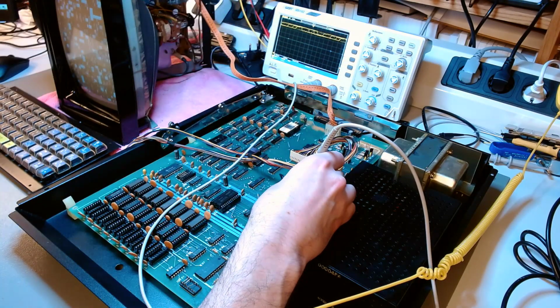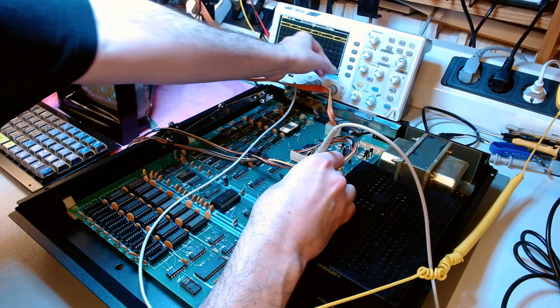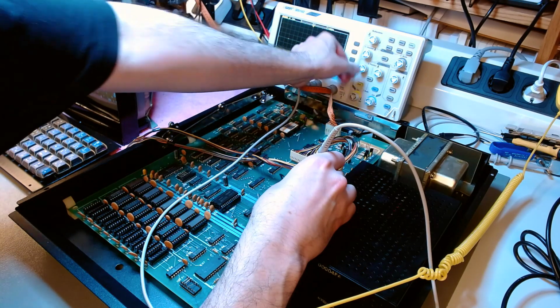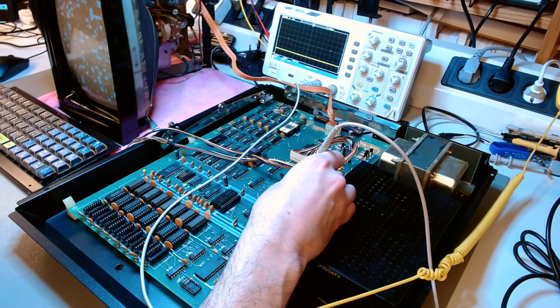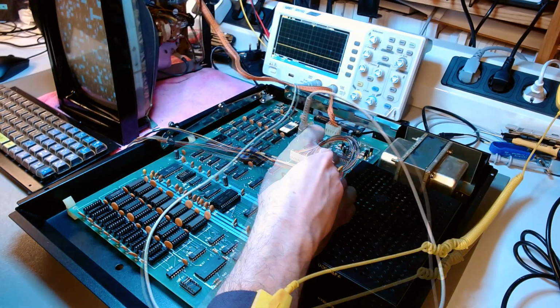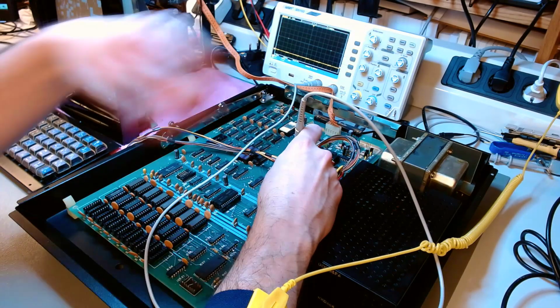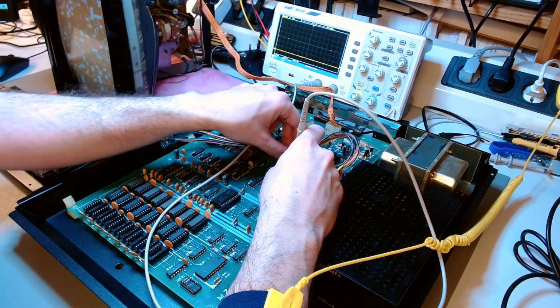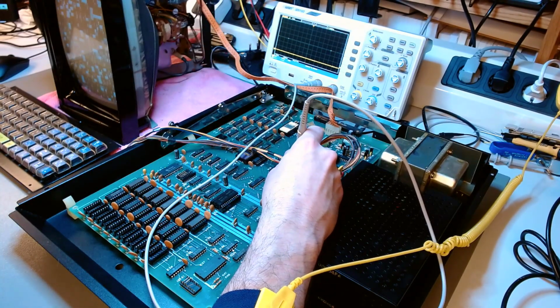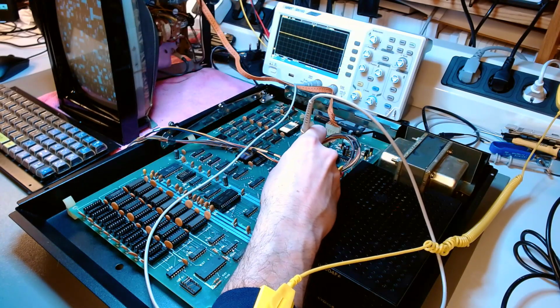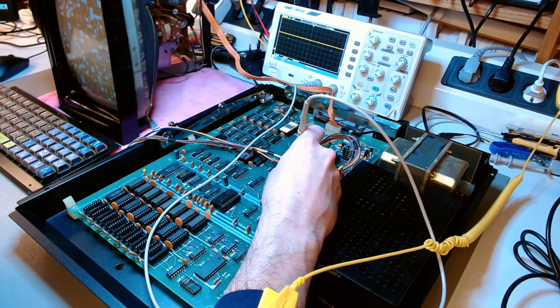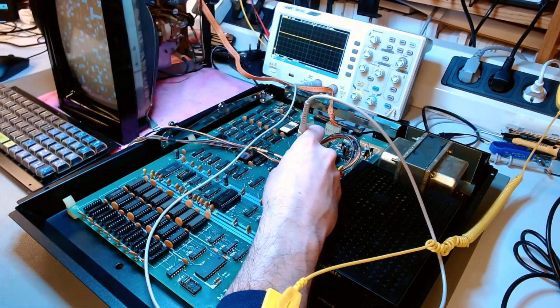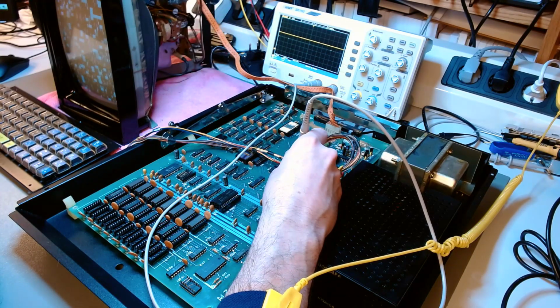But to confirm that, we need to look at the other signals, and that's what I'm going to do now, and I will leave you with my live narration of what I'm doing. Next one is ground. So ground is indeed at ground. So what we saw before is not a ground reference issue. Then we have refresh. Clearly it's always high or inactive, so the CPU is never refreshing the DRAM. Of course not, it cannot drive the address bus.